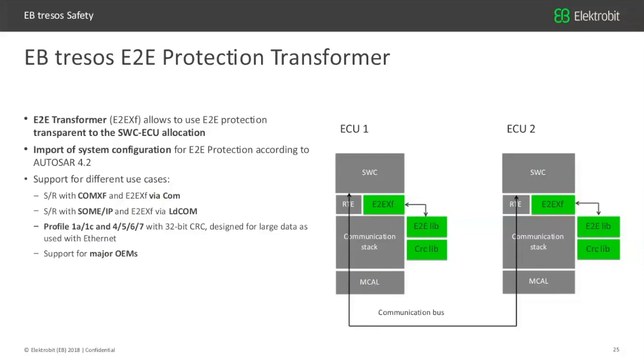which is a normal signal-based communication. So your software component is sending or receiving your signal data on any bus, and is just calling RTE read, RTE write. The same actually works as well on some IP communication or service-based communication, which means you can basically also do the new way of communication based on some IP.